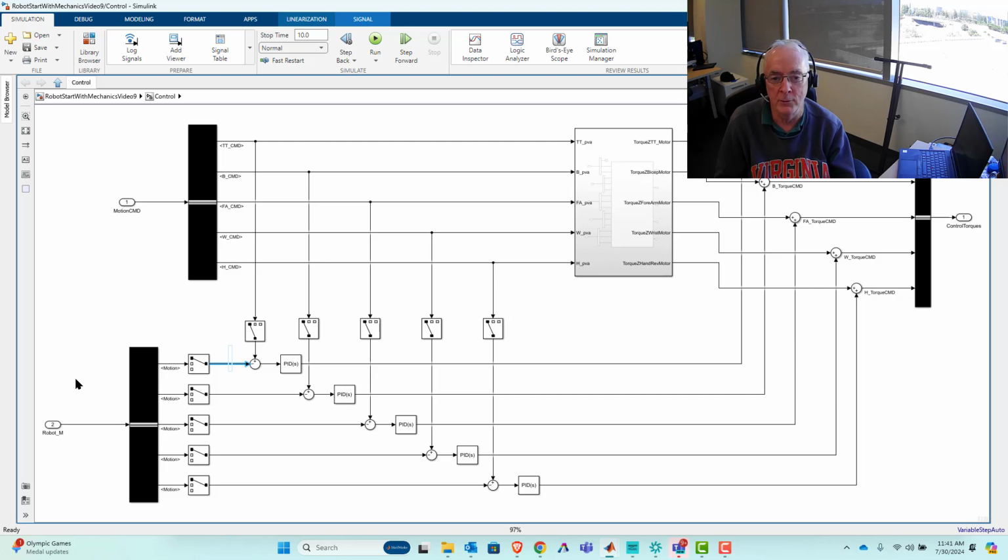Because if you're doing a variable time step method, that's all based on the idea of going back and trying again if you begin to spot a divergence in your calculation. So there's no trying again when you're operating on real hardware, right? And to do this, everything now needs to become fixed time step.